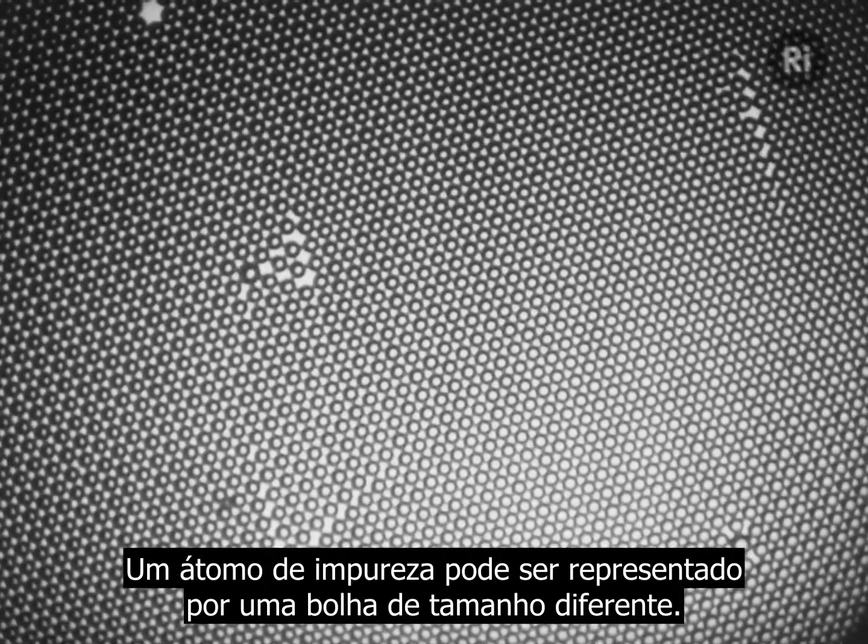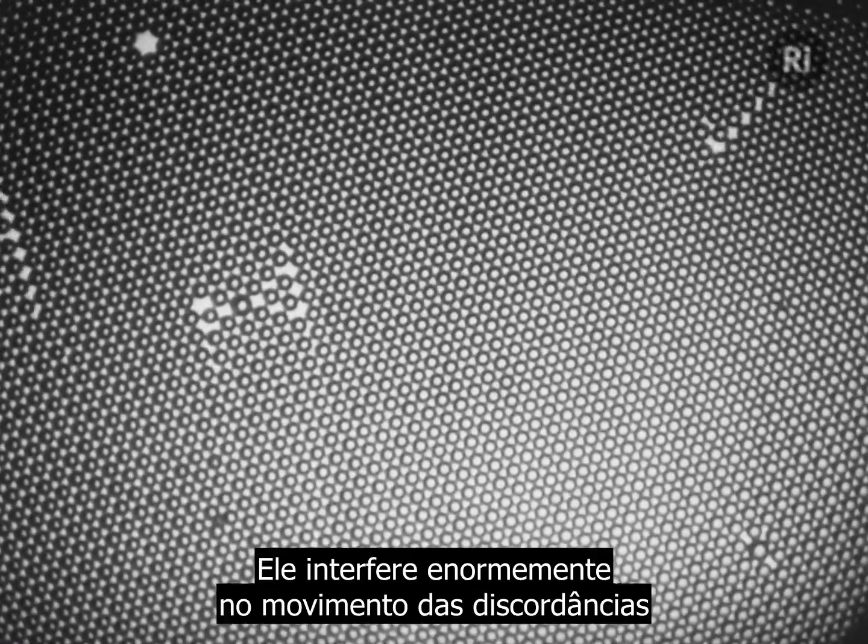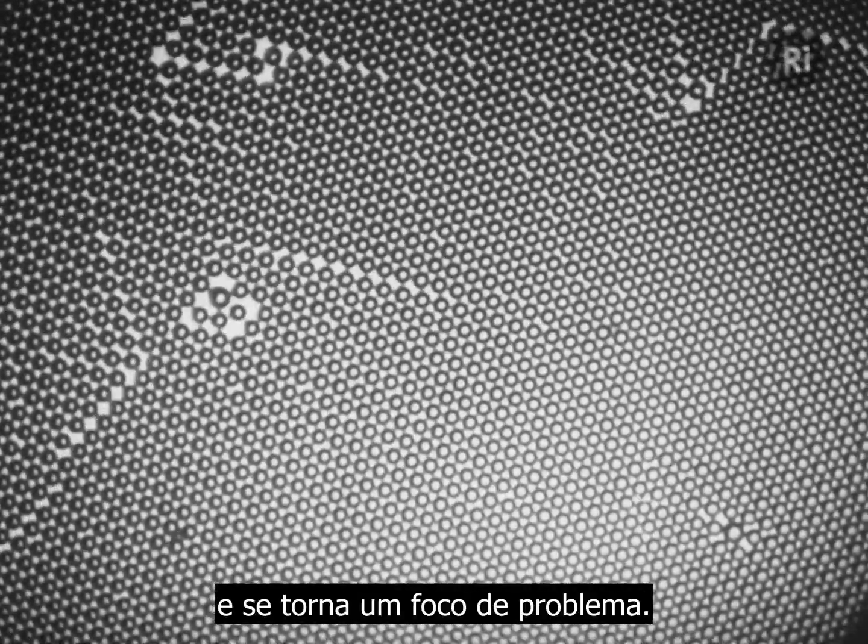Two repelling dislocations are reluctant to pass. One drives the other before it. An impurity atom can be represented by a bubble of the wrong size. It interferes greatly with the movement of dislocations, and it's a center of trouble.